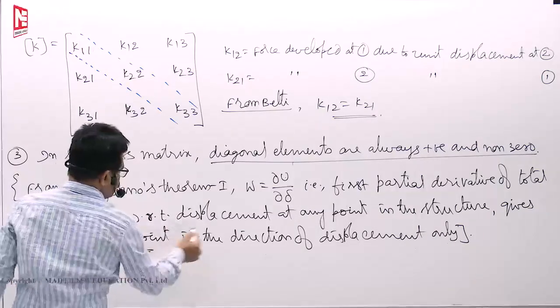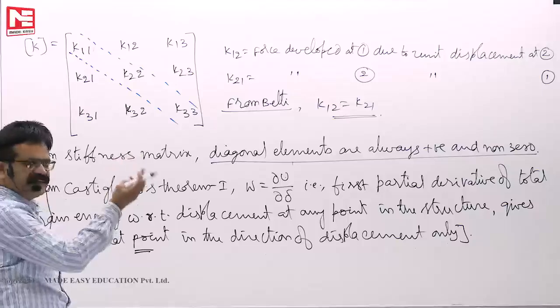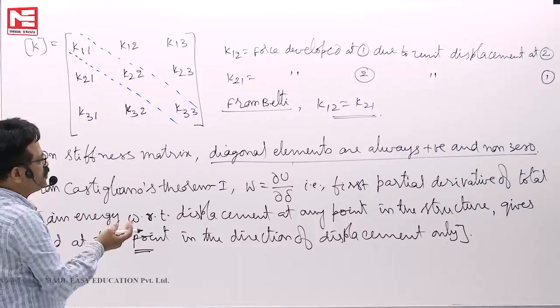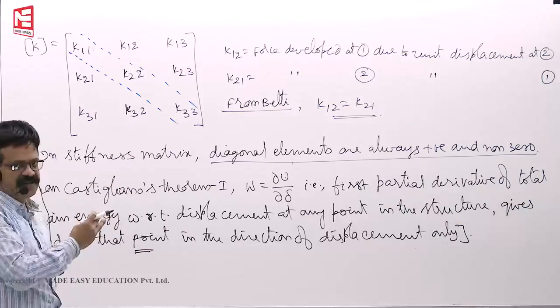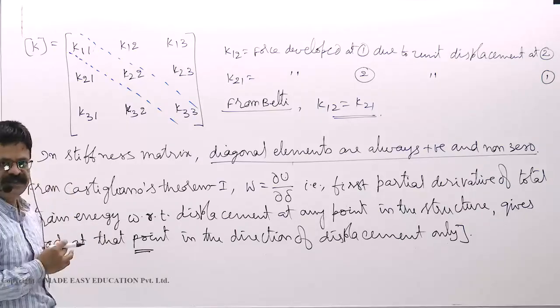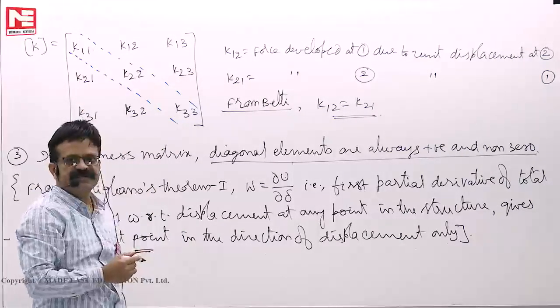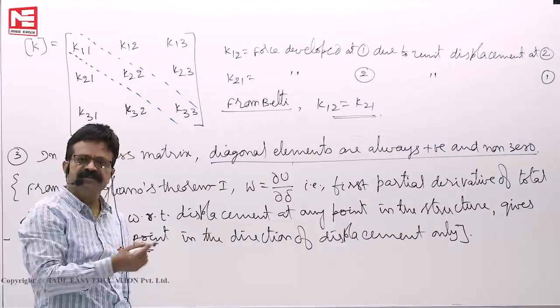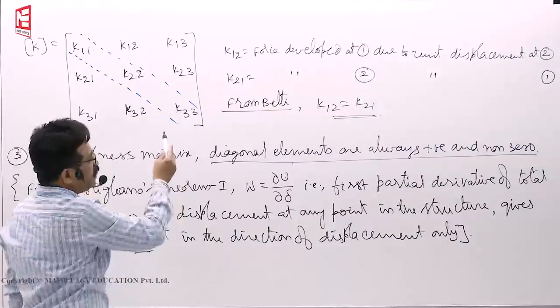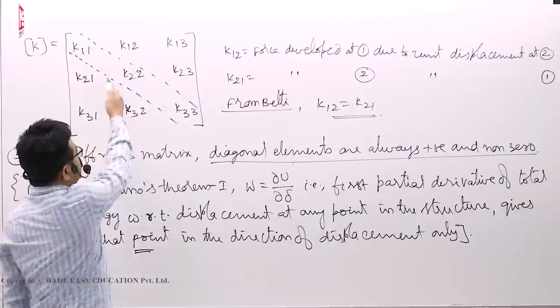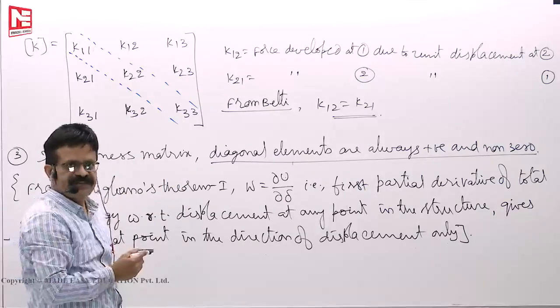then the applicability of theorem 1, I have given you, is to linear and non-linear elastic structures. If it is applied to linear elastic structures, it is called the stiffness method because you are getting stiffness coefficients. Castigliano's theorem 1 is called the stiffness matrix method because by differentiating twice you get the stiffness coefficients.